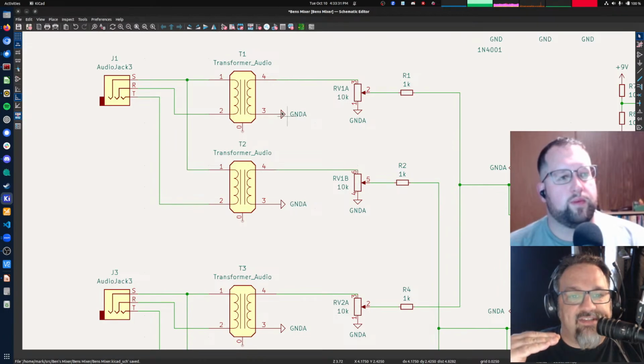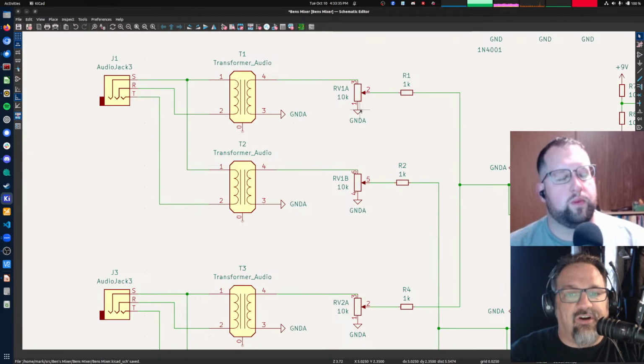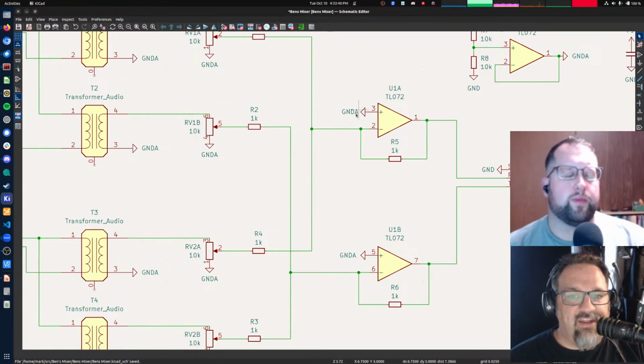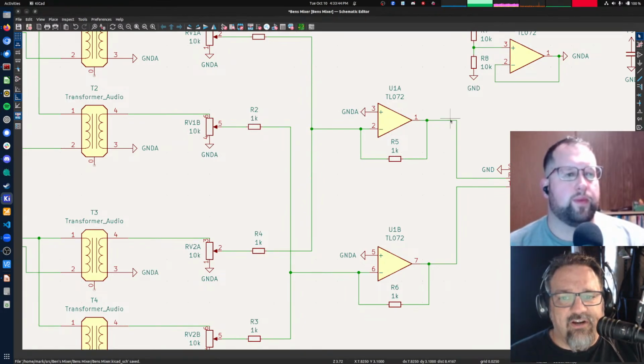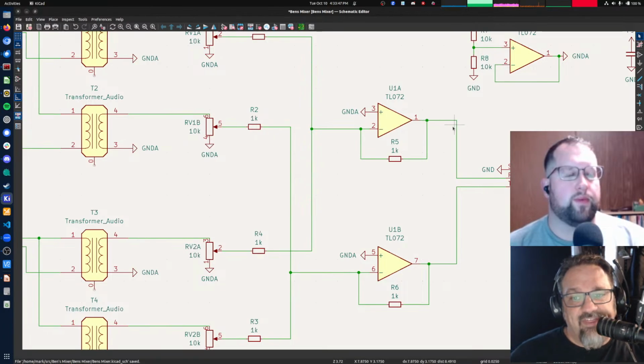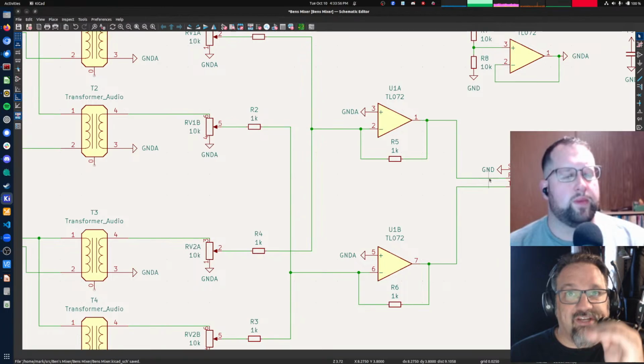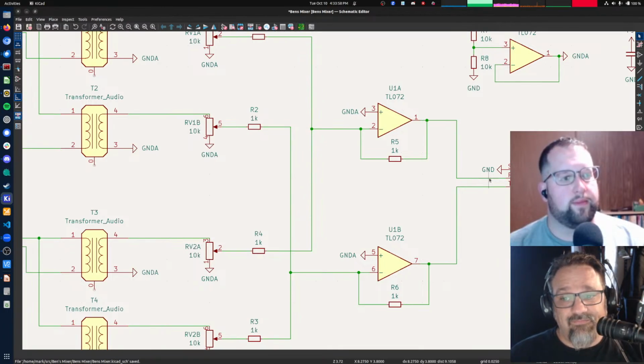And that's okay because that's 4.5 volts, that's 4.5 volts. So all of our grounds are 4.5 volts. And we come over here, the op amp, we've given it 4.5 volts for our ground. So this voltage here will be the same as the voltages over here and everything. So now my signal here is cycling around 4.5 volts. Goes up to 5 volts, down to 4 volts, up to 5 volts, down to 4 volts, into your speaker or whatever your load is here, and then down to ground.